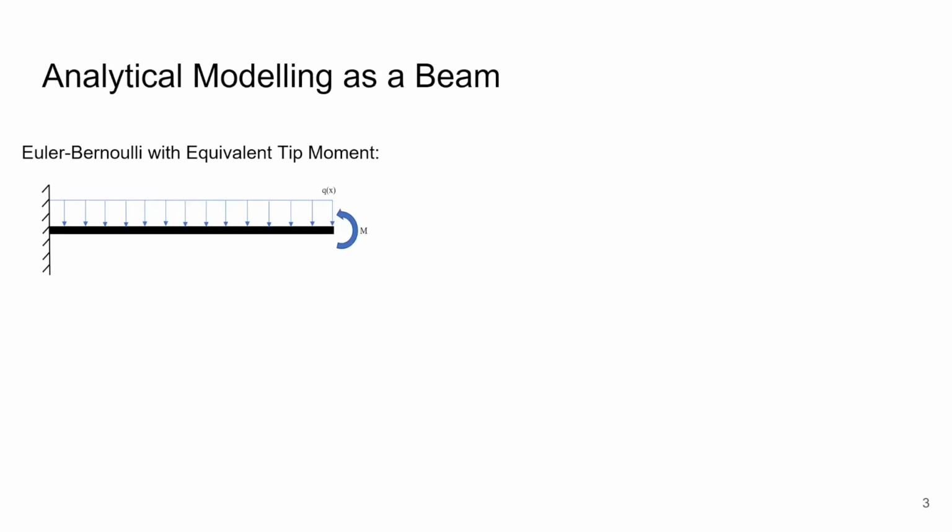For this project, both Euler-Bernoulli and Timoshenko beam theories were used. In developing an analytic model to predict the deformed shape of the panel, we started by applying a tip moment using Euler-Bernoulli beam theory to the end of the plate equal to the force exerted by the F2MC tube times the distance of the tube from the plate's neutral axis.